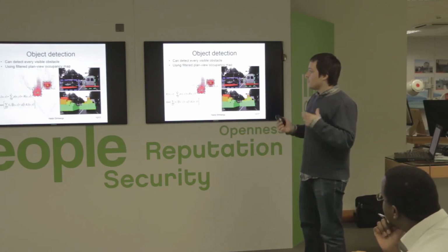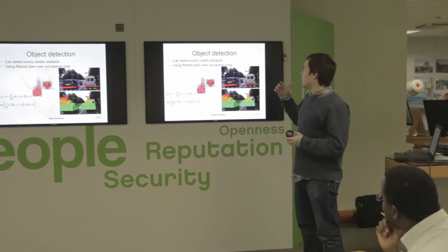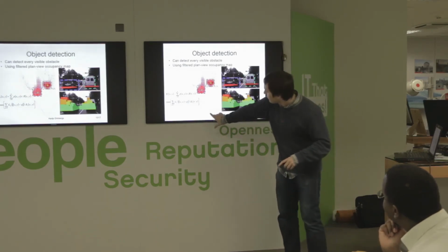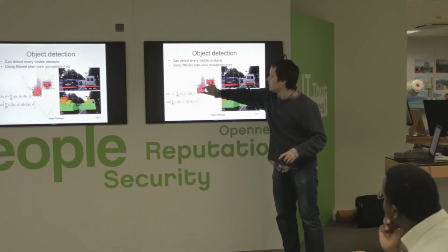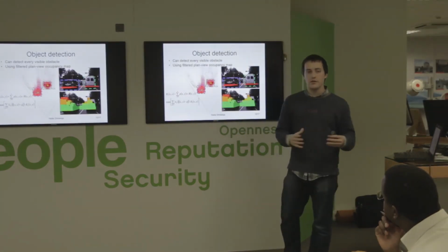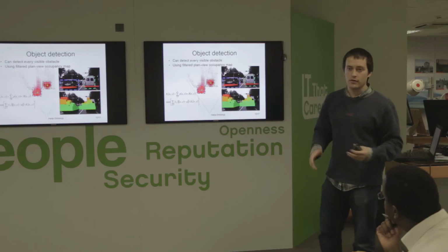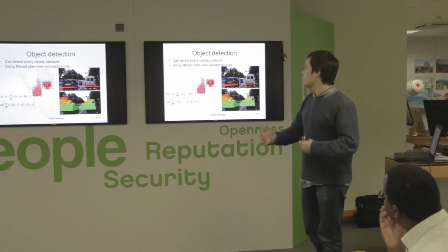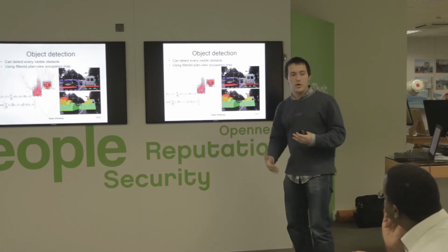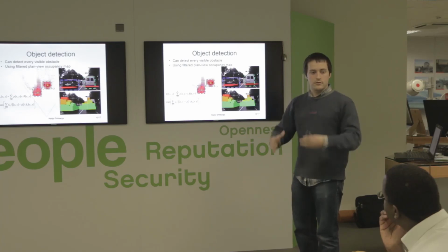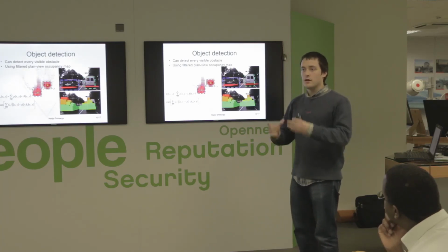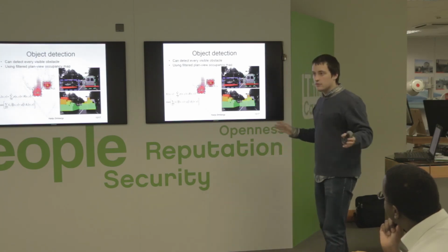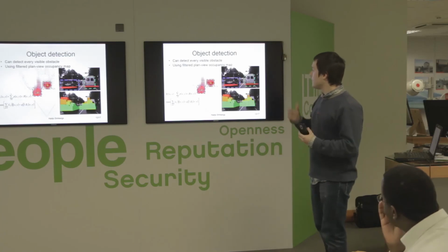That can also be, for example, one of the things I tried: plan view occupancy maps, which is from the top down. So here is the camera, and from the top down I make grids, for example, I don't know, 1 meter by 1 meter or 50 centimeters by 50 centimeters squares, and then I see how many points are in those squares. Walls make the value in that bin much larger. Then I filter it to get rid of noise, and then I actually detect objects.